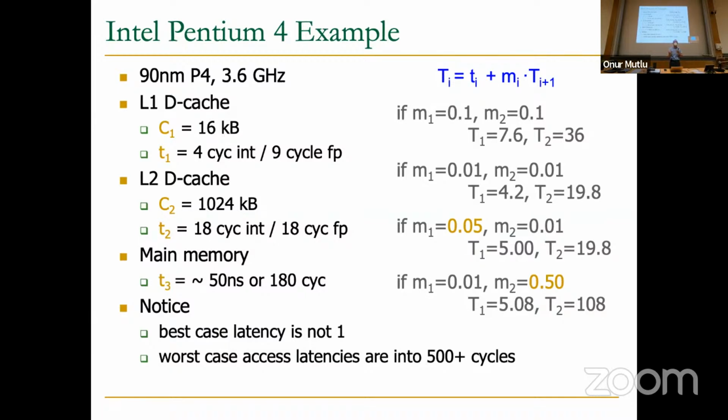What do you try to do if your goal is to make the perceived access time at the L1 level close enough to the intrinsic access time of the L1 level? So that's the richness of the memory hierarchy design, basically. Even with a given memory hierarchy that someone else gave you, you can try to optimize it in many different ways. And the design space is extremely rich. As a result, people have been working on this hierarchy for decades and decades.